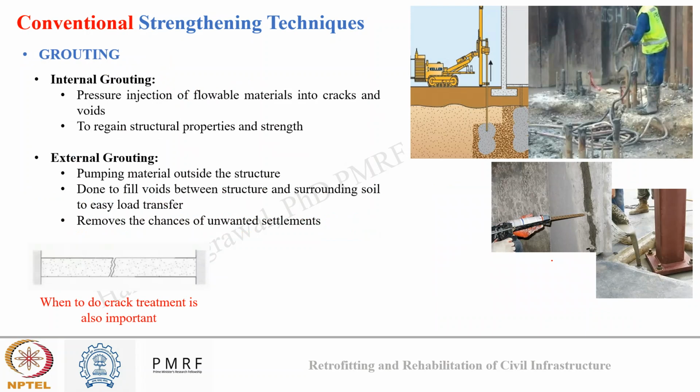Now, the part of crack filling through grouting is clear to us from the last session. Okay, whenever strengthening is applied on a structure, the first basic thing is to first repair the existing cracks on the structure. And a common way is to use the grouting method. Okay. However, there is an additional thing to remember here. In case of crack filling, suppose we have a beam. Now, if possible, the crack shall not be grouted during summers.